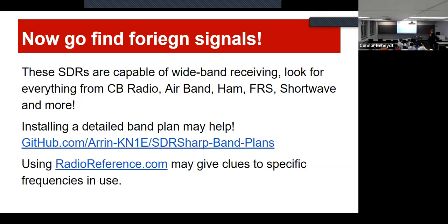Something else, and I'll shut up. If you're into hacking and stuff, look up Tempest. It's called a Tempest attack. With non-properly shielded HDMI or DisplayPort cables, you put an SDR next to them, and you can actually decode the display data using a Tempest attack. Theoretically, if you walked into a secure location with an SDR up your sleeve, put your hand next to the monitor, and recorded that, you can later decode and see exactly what's on their screen. Theoretically.